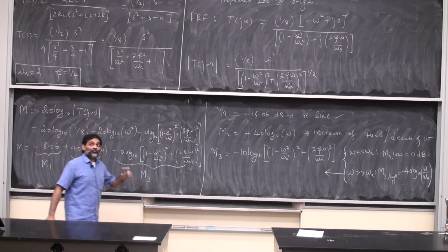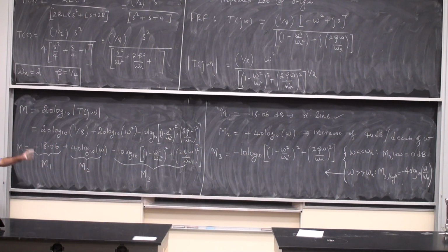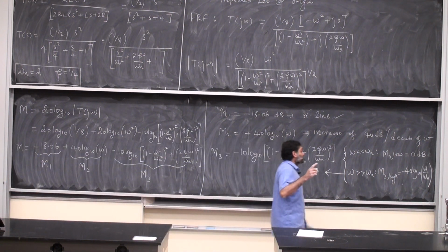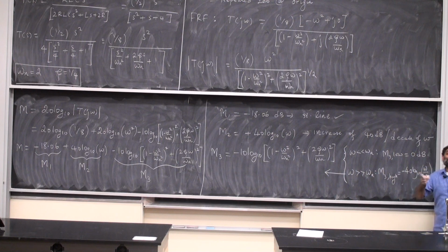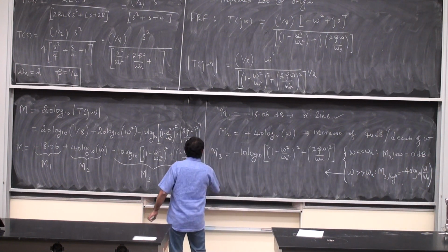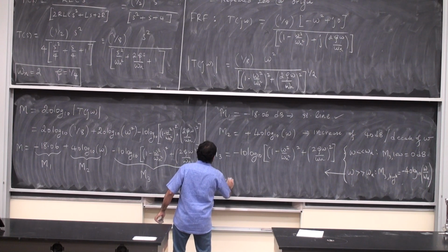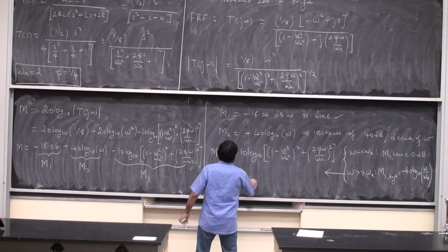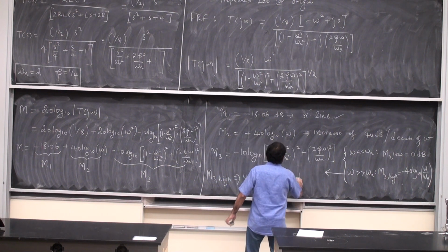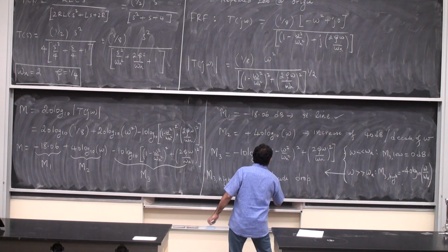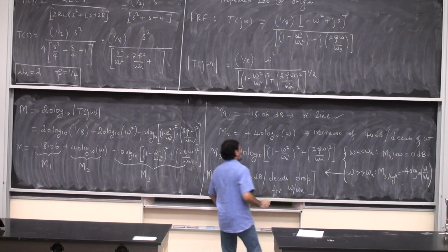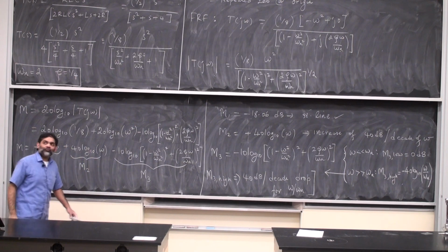The high frequency asymptote tells you that as soon as I cross omega n, which is where these two asymptotes meet each other, I'm going to see a drop of 40 decibels for every decade increase in omega over omega n. So M3 high is a 40 decibels per decade drop for the ratio of omega by omega n.